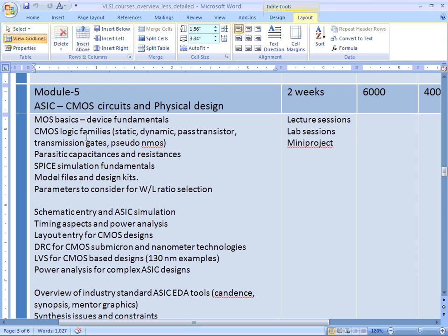There are so many things we will discuss during the course of time. For example, like this. Now somebody has written the code. One portion of the code with rising edge triggering, one portion of the code with falling edge triggering. Now, where these two are talking, the clock time window that is available is very small. Now, this is a bug. People don't expect that you just report this to somebody. You should know what the solution for it is.